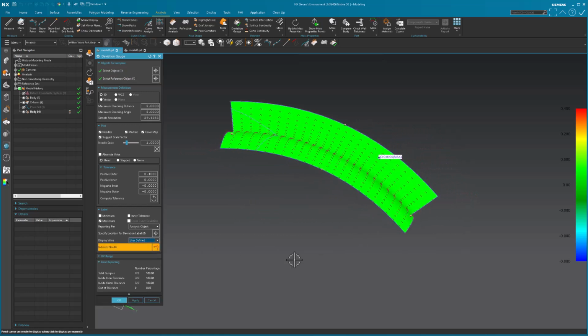And now mind you, this is in metric, right? This is a metric file. I do not see a single anything outside of perfection on that surface. So again, if I sent those control points for that surface to be machined, I will, in essence, be programming perfectly every single time to the exact surface that I need. Because those control points drive the shape. Those control points make that surface.